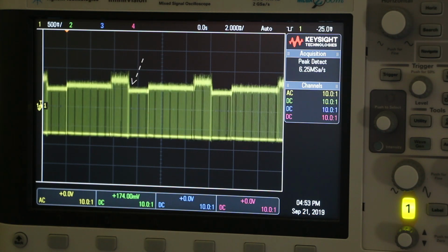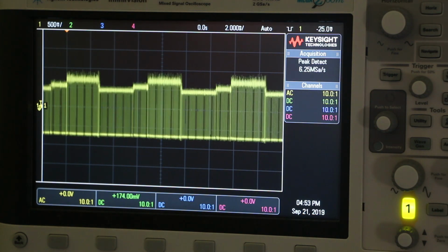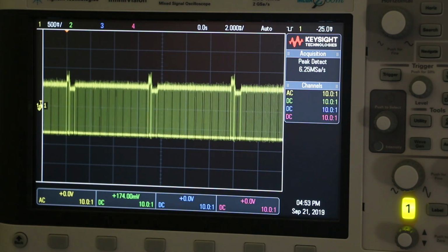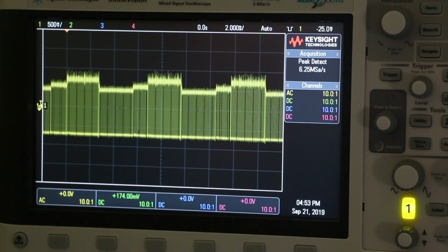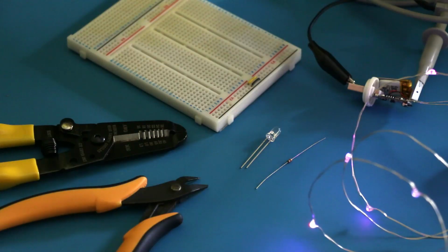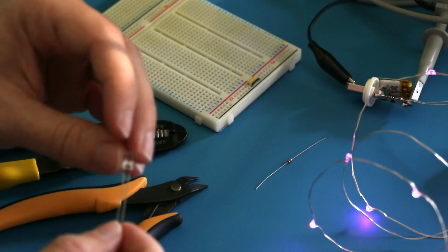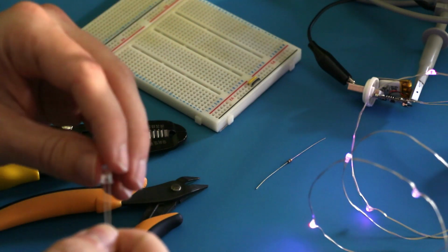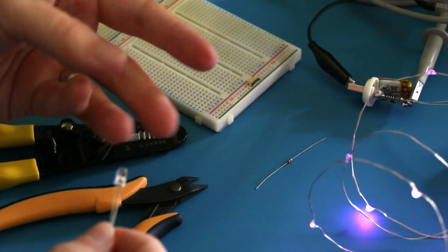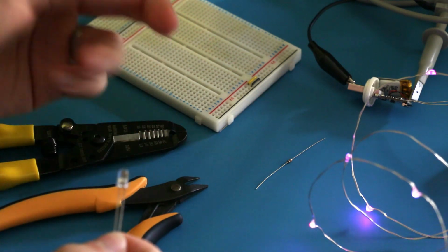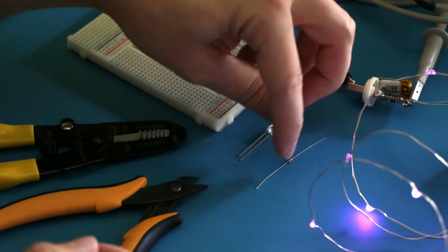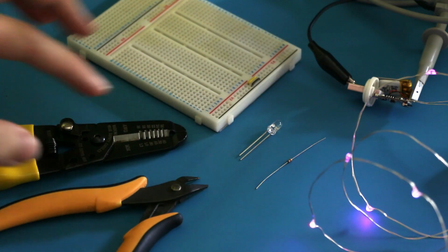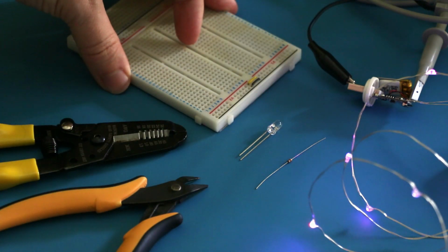So I'd like to try something now, using a photodiode to actually hold up against the LEDs and provide us with a nice digital signal which would hopefully give us the start of the period on the display. I don't actually have a photodiode to hand, but I do have this LED of unknown colour and origin. Obviously, forward biasing it we should get some light out, but reverse biasing it I believe we should be able to get it to react to light fed into the front. And I have a 1K resistor. So I'm just going to put this together on a breadboard and see what we can get out.